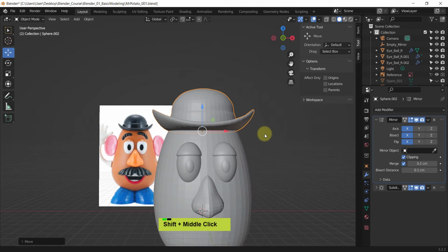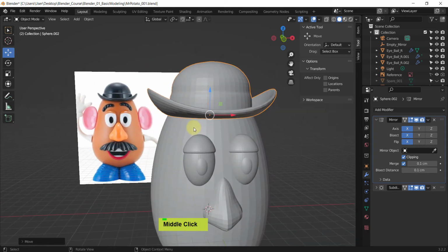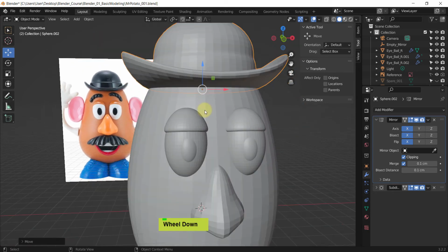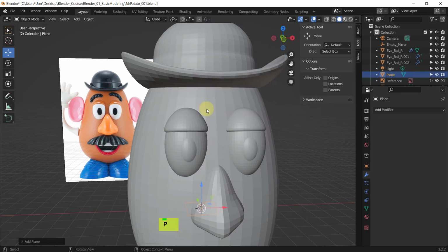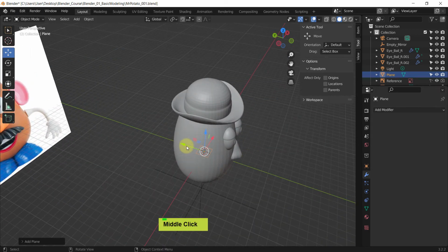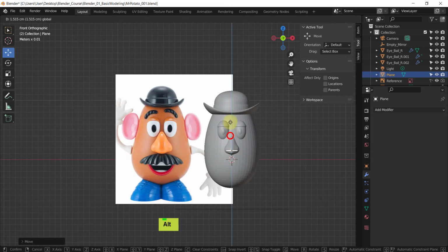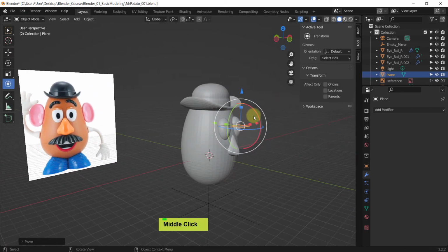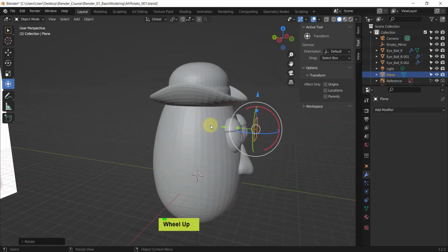Eyebrows are a little bit different animals, because we need to generate them on a surface. So what we'll do is create a plane. Here we are, Shift A, mesh, plane, and that is created at the very bottom. So we'll lift this up, go to the front mode, and use Shift Space T, rotate, and Control to accurately rotate 90 degrees.